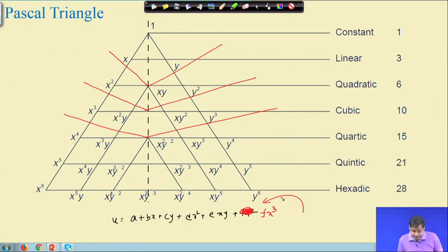So, this is not a complete polynomial, with completeness with respect to both coordinate axes. When you follow this rule, you have an expression which is complete, and that is very important for getting convergence. We will discuss convergence shortly. That is the reason why, when you take this approximation, you have to be careful about which terms you take.